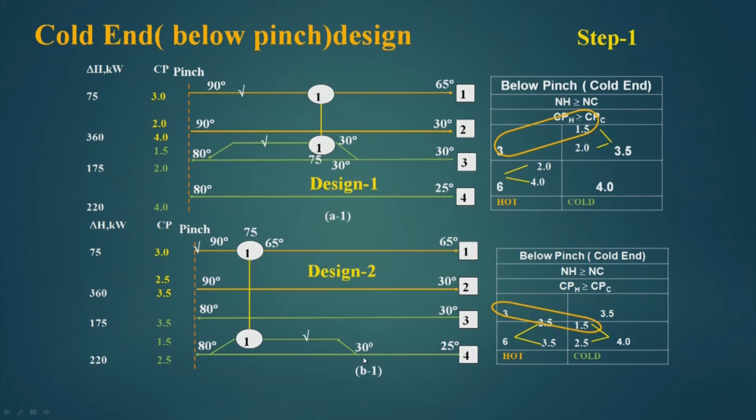Here the Cp becomes obviously 4 from this part to this part, but for this part it is 1.5 and for this part it is 2.5. Now, this 1.5 has come with the same argument, that I have to tick off this stream which has got a delta H of 75. If I break it at 1.5, then this is from 30 degree to 80 degree centigrade.